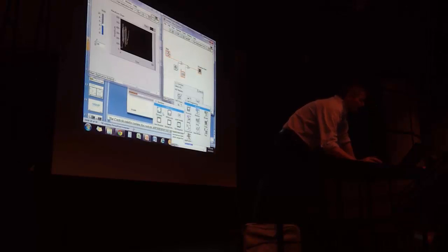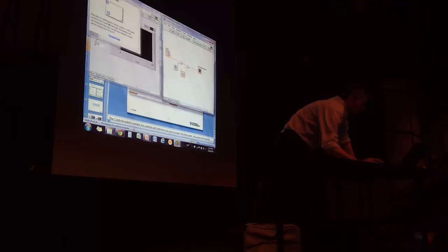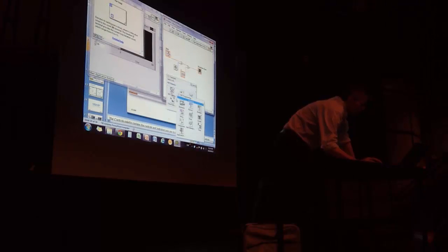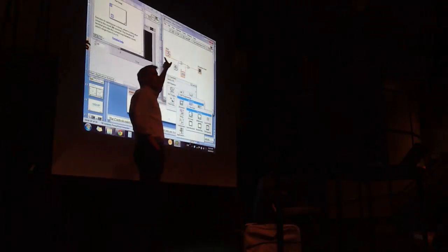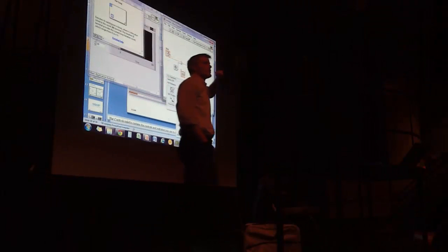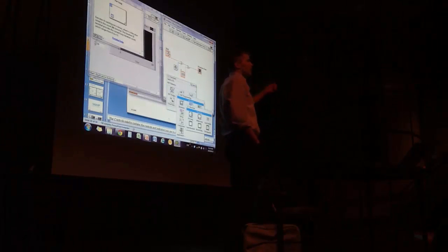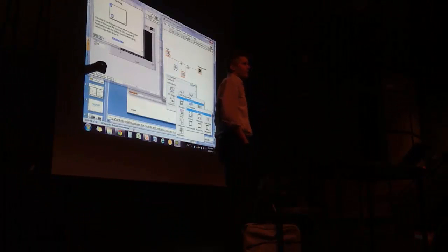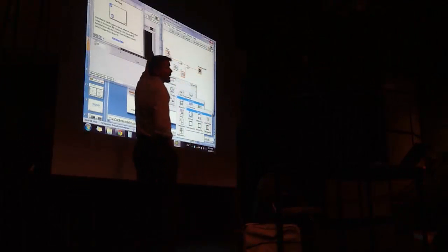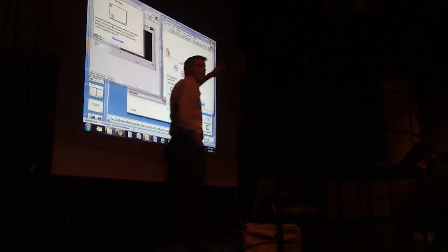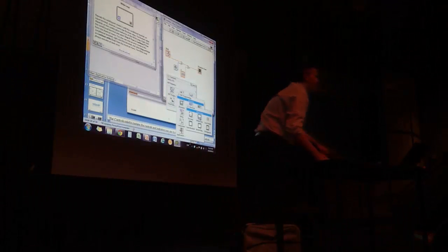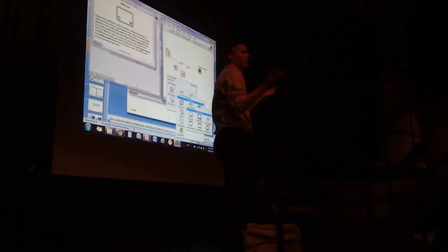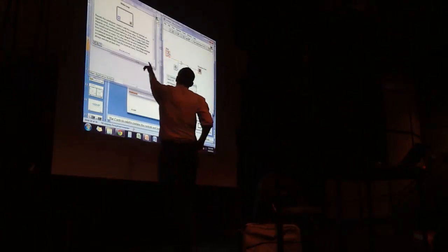You have two different loops up here. This is the for loop. What you see with the for loop is that it has an n input, so it runs for n amount of time. If you say, I want to generate 10 points, then you use a for loop, and you just wire up 10 to the n up there, and it would execute exactly 10 times. On the other side, if I want to run it as long as I want, until I press the stop button, I use the while loop.